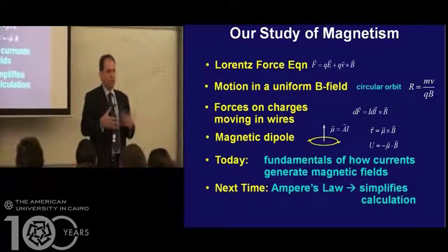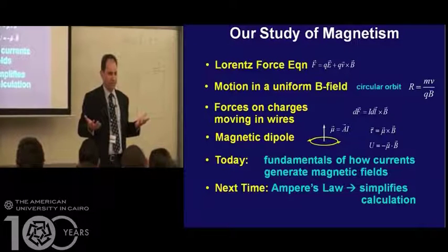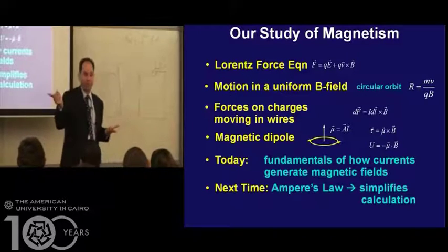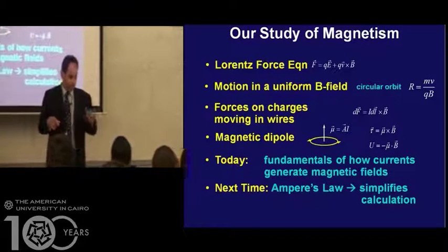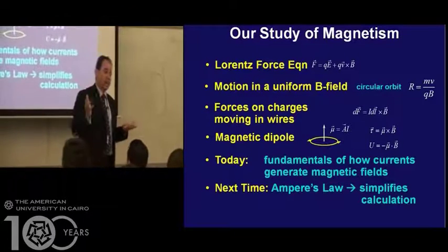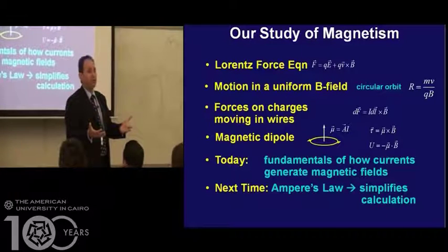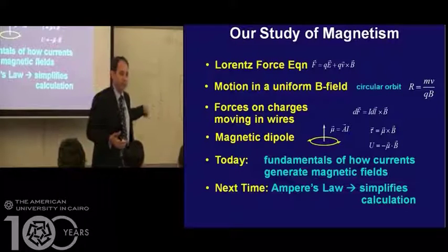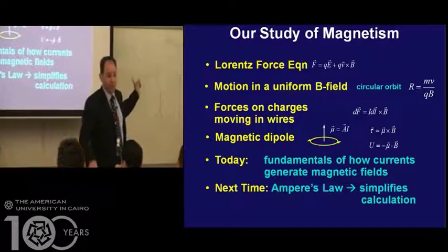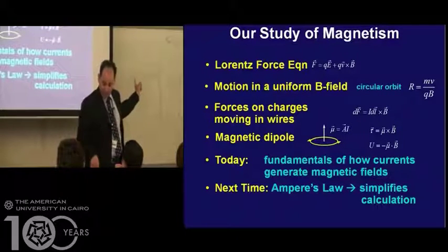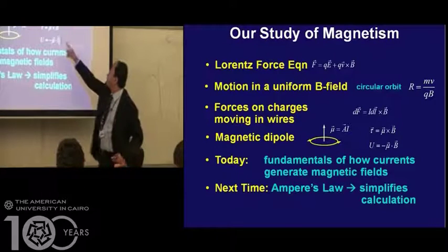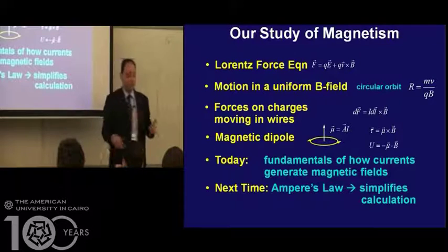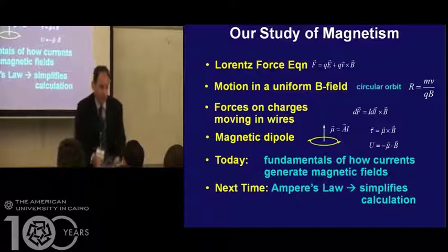And usually the force we can do is our weight. This is how much force we can do. This is the assumption that you need to make in the assignment, for the people who have read it already. So if you assume that your weight is 100 kilogram, then you calculate how much force you can actually do. Then if you know that distance, you can calculate the torque. And if you compare that torque to the magnetic torque, then you can simply see if you can actually stop it or not. Now, in that case, obviously I can stop it.